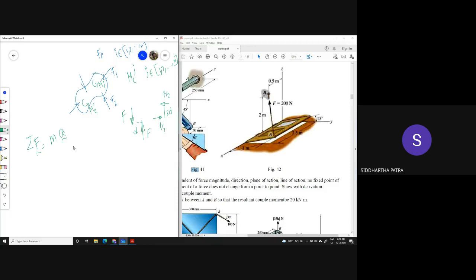When you use it for a rigid body, you have to understand that not each point in the rigid body is equally accelerated. If all the points were equally accelerated, the rigid body would only be doing translations. Since it is also rotating about some axis, there has to be only one representative point, and that representative point happens to be the center of mass.